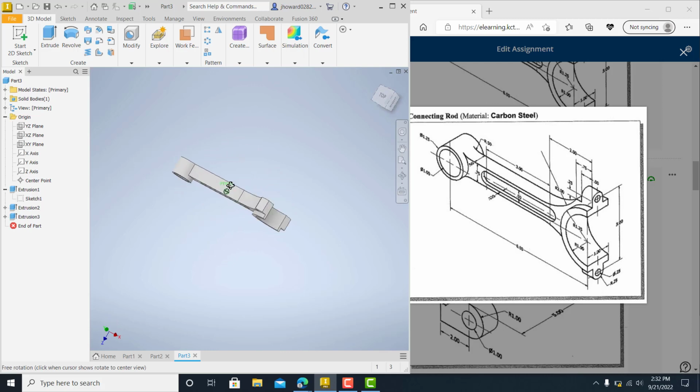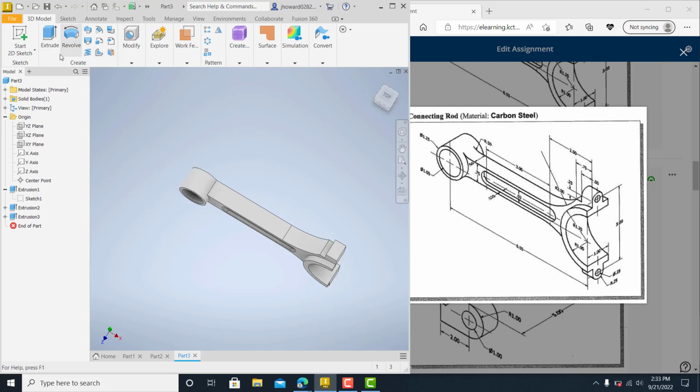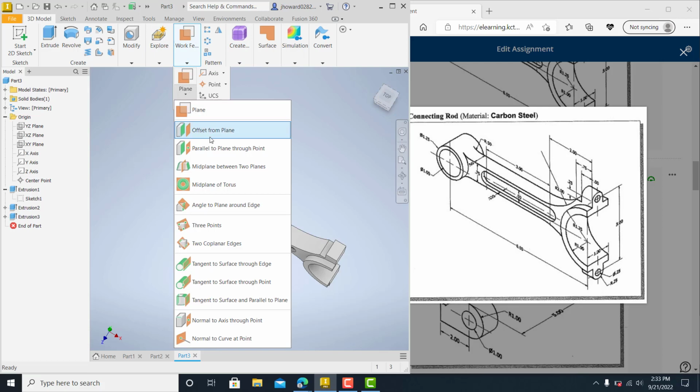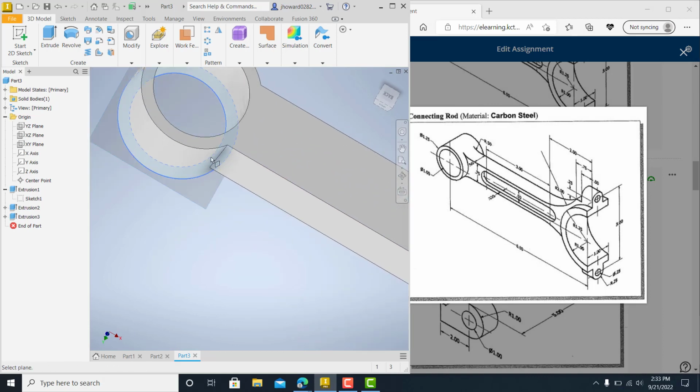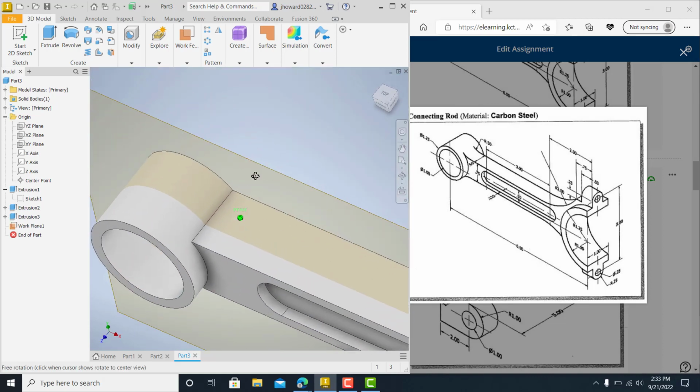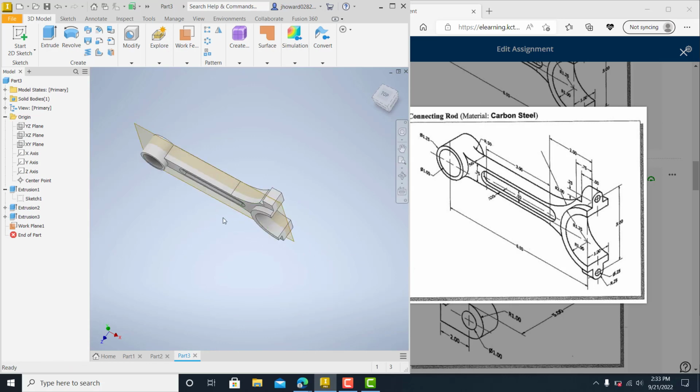And what I want to do now is I want to make myself a midpoint plane. Okay? And there's all kinds of ways, I mean, I could go to the other side and do what I did here and cut that out, but check this out. I can go in here and go to Work Features, Plane, and do Midpoint Plane. And in that I can catch on this side to this side, and it puts myself a plane in there. Do you guys see that?